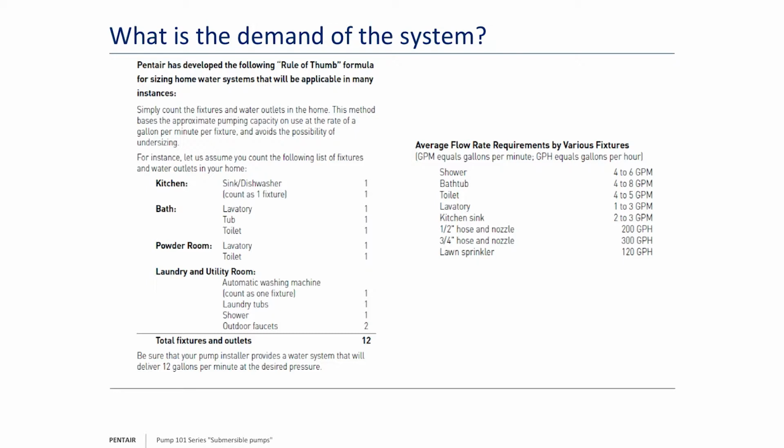That means from 100 or 50 feet, wherever that water surface is, down to the bottom of the well in a 6-inch casing is water storage. And understand that for every foot of water in a 6-inch casing, that's 1.5 gallons of storage. So they will pump that well clear down almost to the bottom using the well casing as a supply.